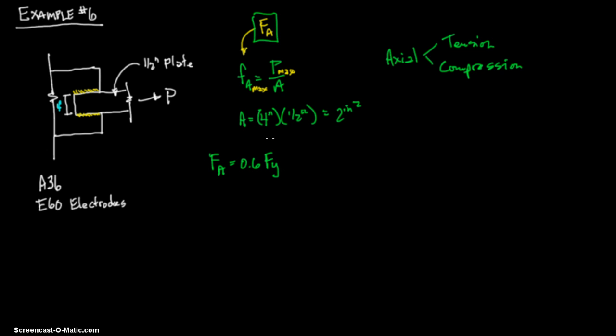And I know that bending is 0.66 Fy, and I know that your shear stress is 0.4 Fy. But I want to find it in the steel book so you can look it up and know where it is. The place where I would start looking is where it says spec. I would go to that, and that's the specifications. This is really the meat and potatoes of your specifications. If you just want to go in there and look this over, it'd probably be well worth it.